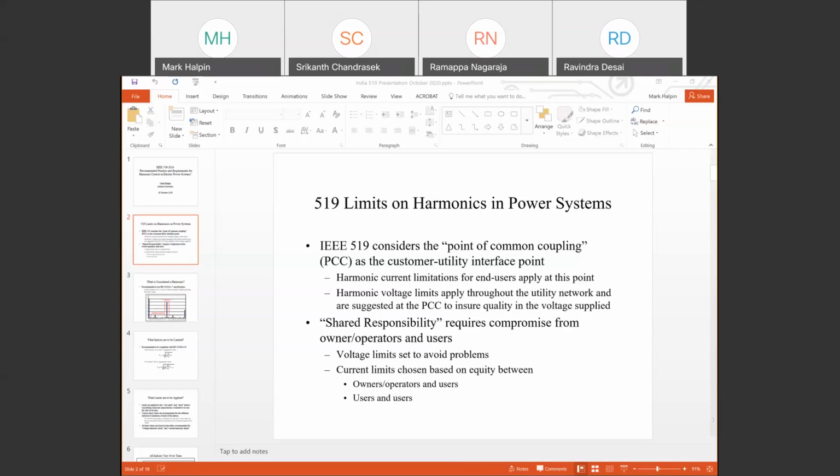And there are two aspects to voltage quality. There are two main factors that affect it. Number one is the impedance characteristic of the network. The impedance characteristic is largely managed by the utility company and largely influenced by the impedances of the T&D system and various pieces of equipment. The second major factor that drives voltage quality is the harmonic currents that are produced by network users.